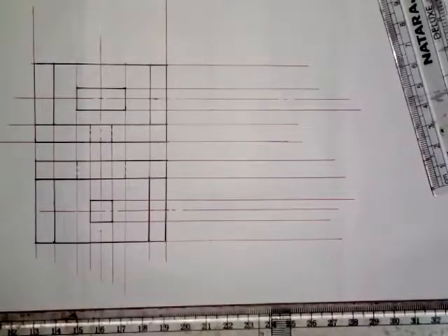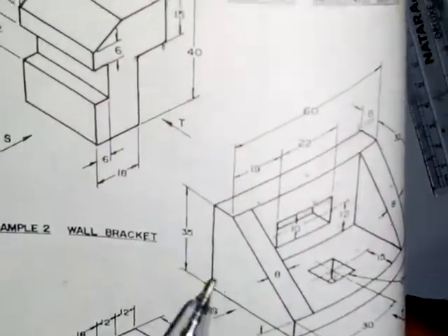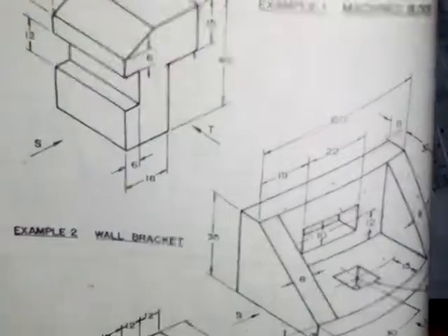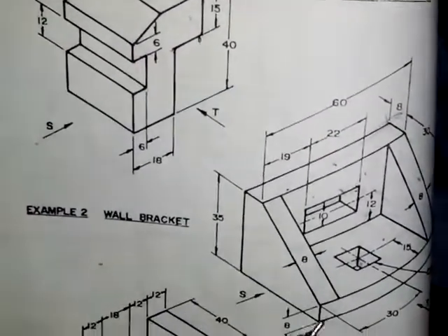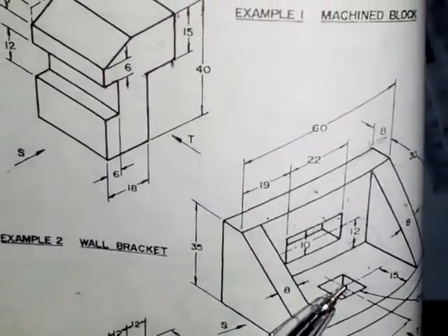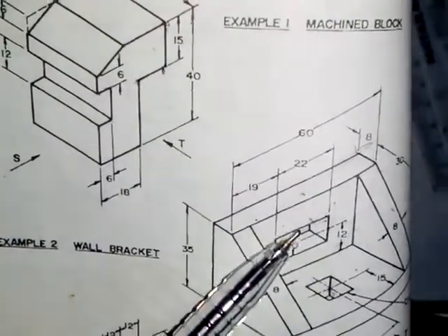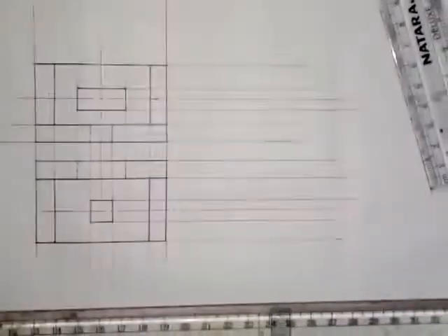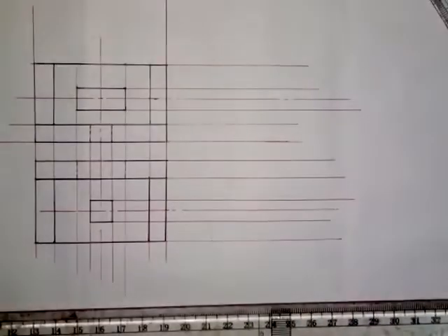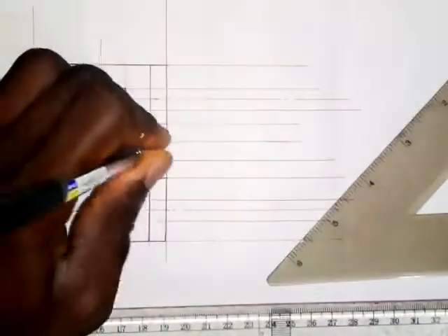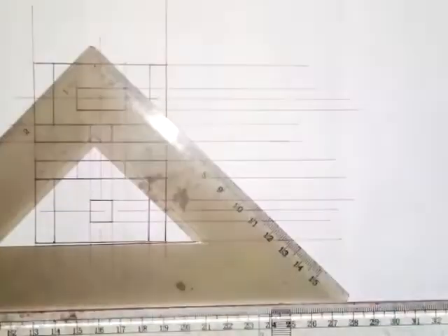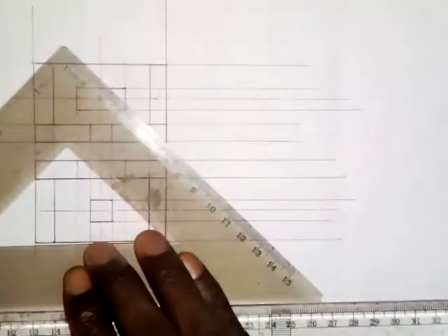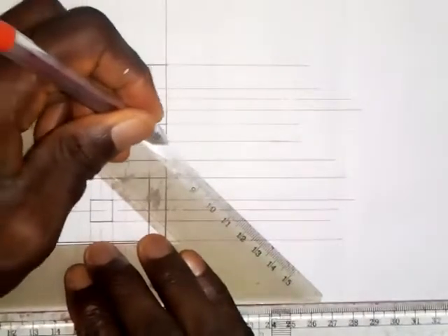So that is the plan. The next thing that we are going to do is to draw the end elevation in the direction of the arrow, as we are told. So I just want to bring out this shape like this. Then this hole will be hidden, and this will be hidden. This will be hidden within this part, and this will be hidden within this part. So everything is already here on this side. All you need to do now is come to this point on the front elevation and draw an inclined line with your 45-degree set square. So draw like this.